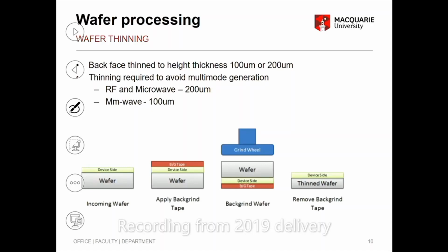So you have to convert that way because your microstrip line width is determined by the characteristic impedance, right? We covered characteristic impedance earlier. So for 100 micrometer thick, I have to pick, I don't know, 50 micrometer. What is it? Can you guys remember what the width is? I think in lab 2 we used the right width. So for 100 micrometer thick, say we have to use 20 micrometer with metal 1. If I don't make my wafer 100 micrometer and keep it 200 micrometer, my impedance drops, right?